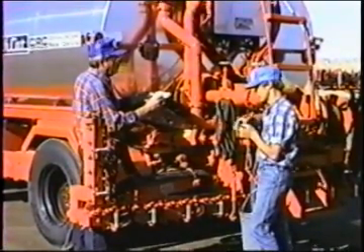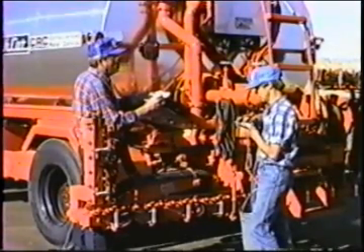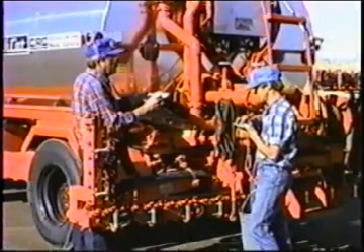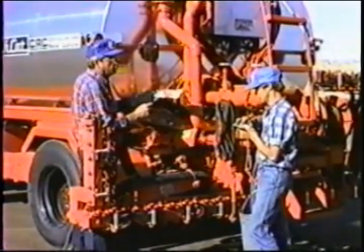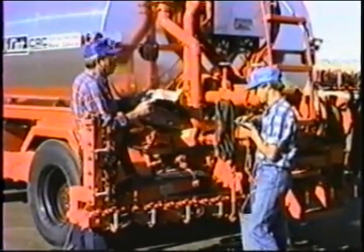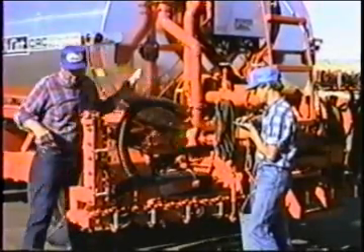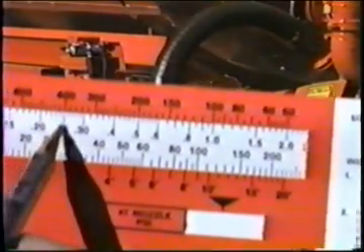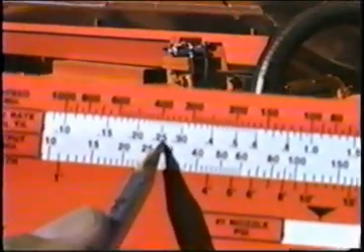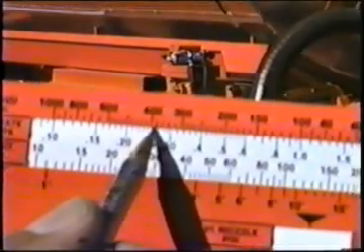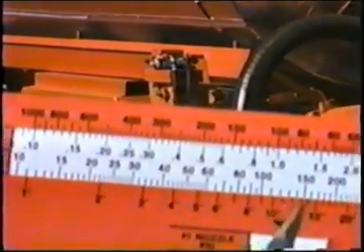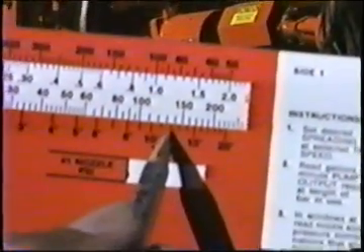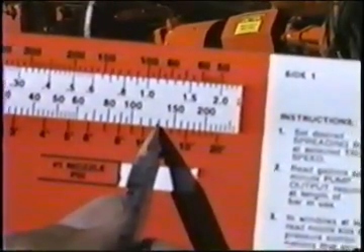Underneath that, on the bar length, he told you 12 feet. Okay, if I line up 12 feet, I see exactly 135 gallons per minute. That's correct. That lines up with that. 0.25 gallons per square yard, 400 feet per minute, 12 feet wide, 135 gallons a minute.